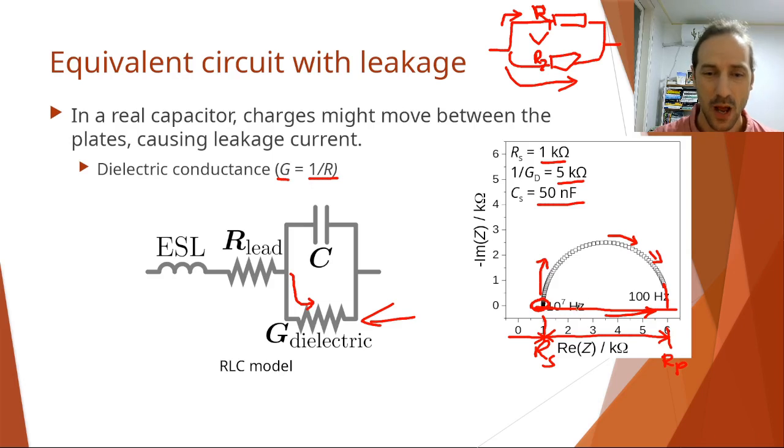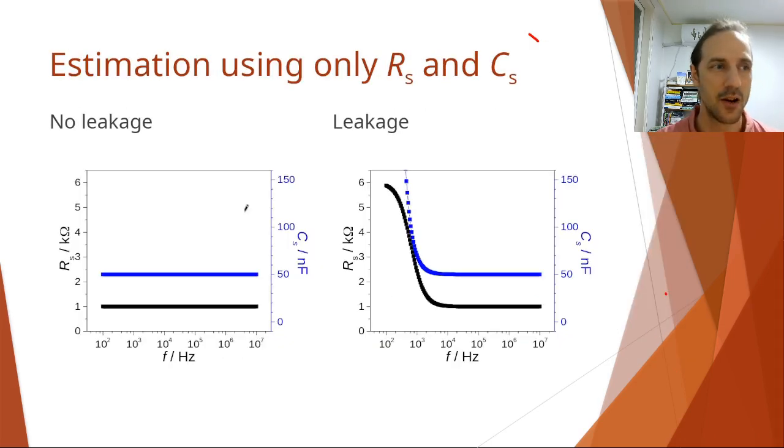And this is basically what I'm saying, like moving this way, because usually when we measure the capacitance, we start with the high frequency and then we go down towards the low frequency. So don't get confused about that. Now let's take a look at the next slide here. Usually when we measure the capacitance, or rather the impedance, we just calculate the series resistance and the series capacitance.